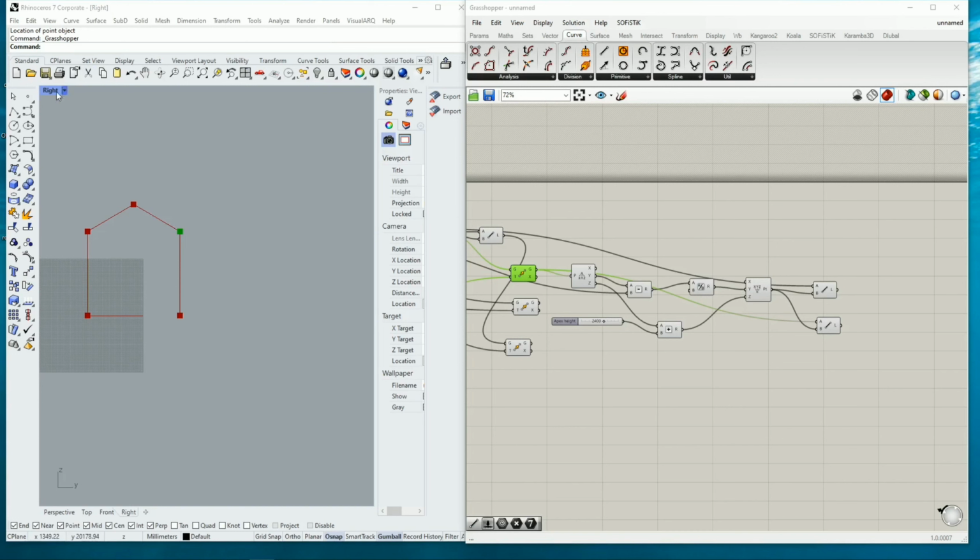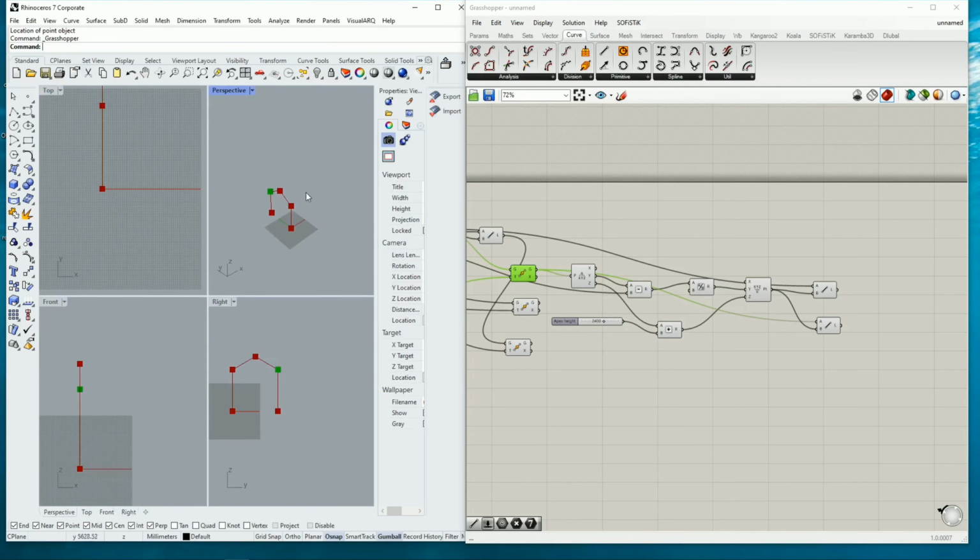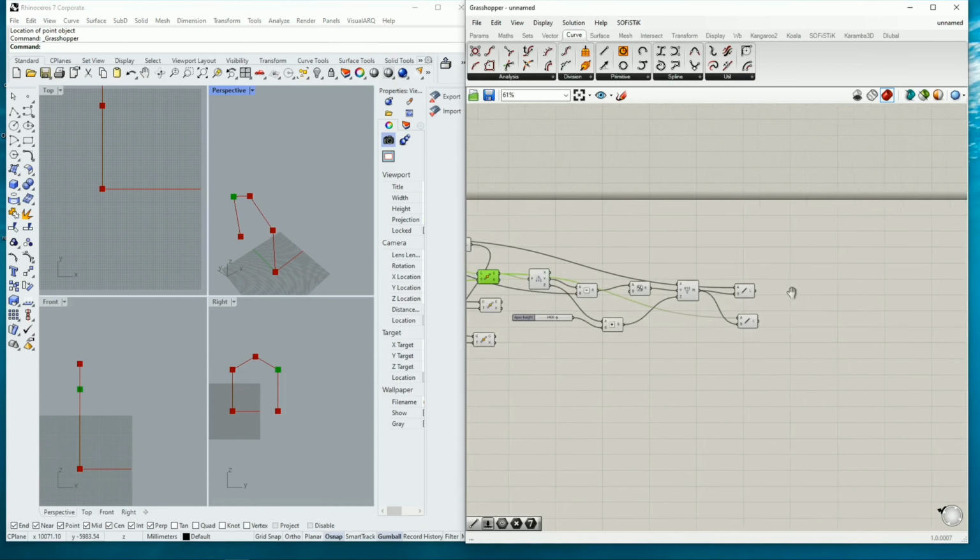So the next in line to turn this to 3D is to do what we call a series copy in sequence. And we have to take this at different intervals. So we need a copy of this in, say, 5 meters interval with the number of copies we need. So that is the next thing we are going to do right now.